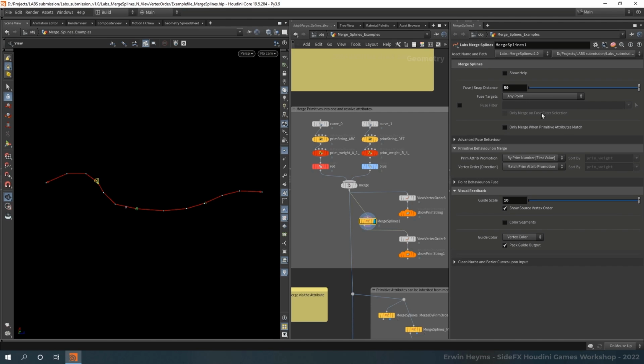So in this case, I have snapped it using a snapping value up here. If I lower this, notice how the curves don't snap. And if I increase the value, you'll notice how the curves will start merging. Now, if I set the value too high, the curves will start snapping to themselves, and then you won't get a good result. So if you want to, you can also specify that it should only snap the endpoints or any endpoints and intersections. So that, even if our snapping value is very high, it will still merge the curve into one.